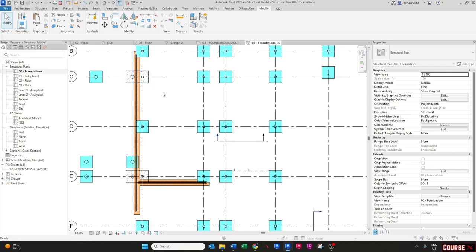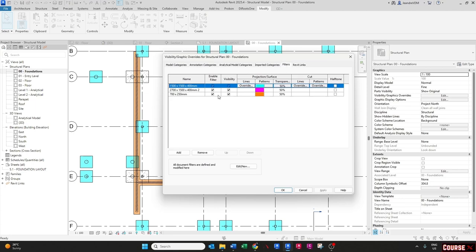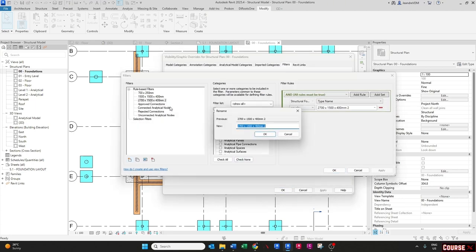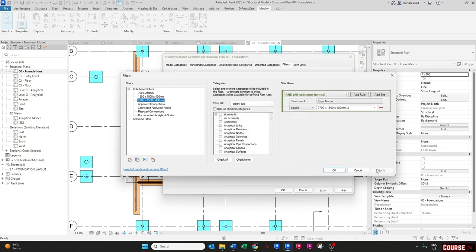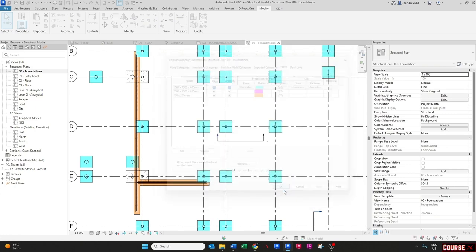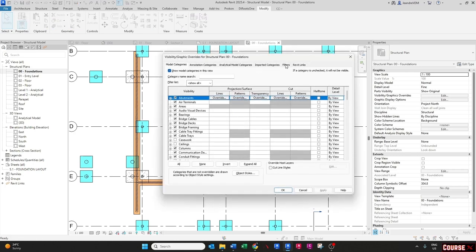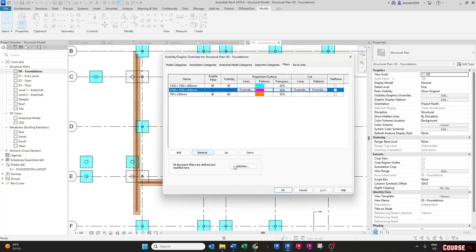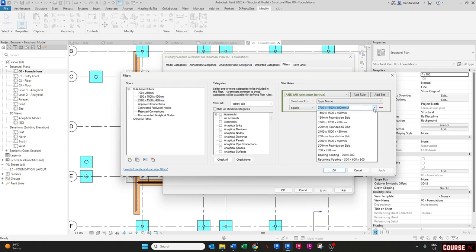So if you go to VV again, filters, you can change this name like I said earlier. If you change this name, show you and say okay, okay, okay. It doesn't do anything. This name can be whatever it wants. It's the other name within the rule that's the governing factor. So I need to change this to that base. Apply, there, change the color.